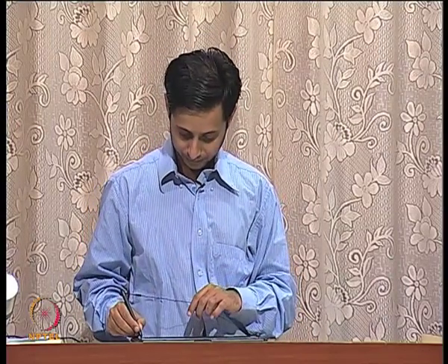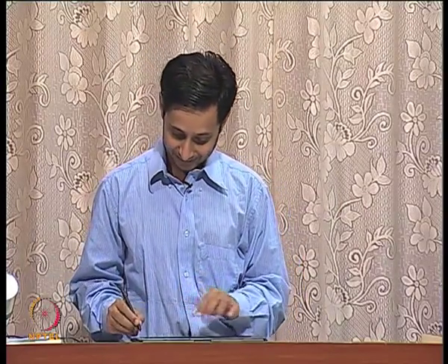So, if instead of a circular cross section you go for a rectangular cross section, things will change. As an engineer, I do not really care about these small changes. I need some intuitive understanding of what is going on, and this result gives me an intuitive understanding. That is good enough. Okay. Oh, one more thing, as you make your wire thinner and thinner, the inductance per unit length becomes more. So, thinner wires have more inductance, thicker wires have less inductance. Interesting. All right.